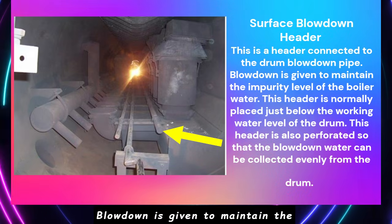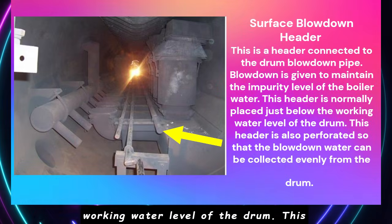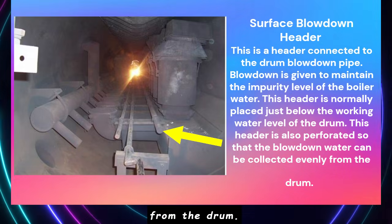Surface blowdown header. This is a header connected to the drum blowdown pipe. Blowdown is given to maintain the impurity level of the boiler water. This header is normally placed just below the working water level of the drum. This header is also perforated so that the blowdown water can be collected evenly from the drum.